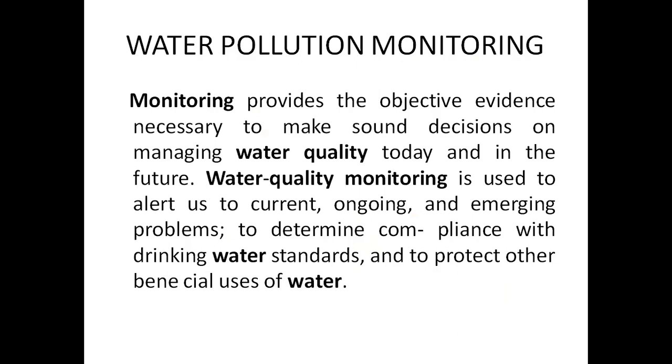It has a wide range of sampling methods depending on the environment and the type of material being used. The types of water sampling include judgmental, simple random, stratified, grid, systematic, adaptive cluster, biomonitoring, remote sensors, passive, semi, and continuous grab sampling. The chemical condition of water is of high importance, so the presence of oxygen, nutrients, oils, pesticides, and metals are all monitored.